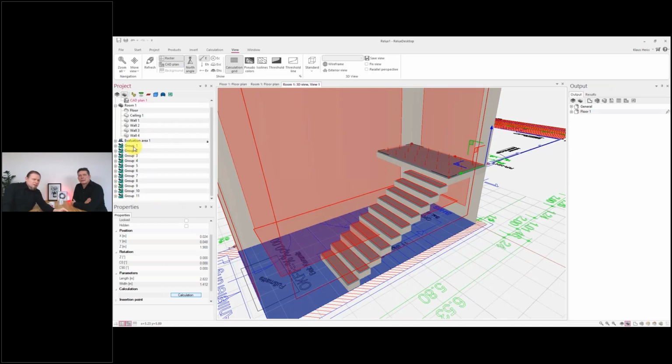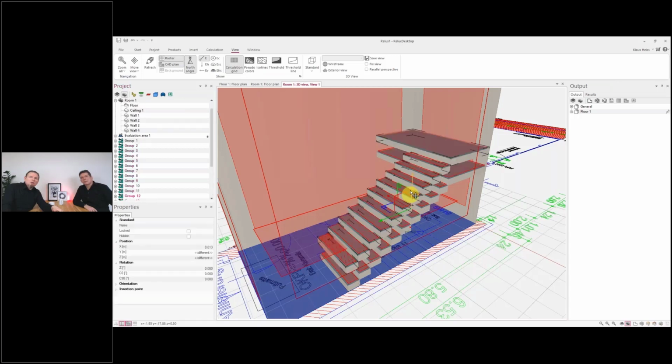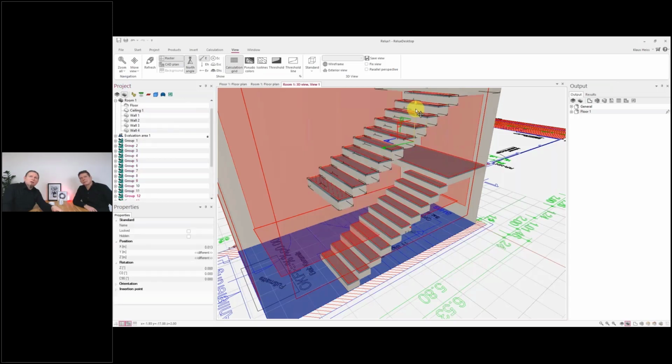In this situation, I just mark everything. You can also group everything, it's also possible, but I just mark everything. That's enough. Now I hold down the control key on my keyboard, and then I use the Z coordinate, click once, and make a copy. You can create a copy by holding down the control key just in the beginning, and then you can move it freely around.